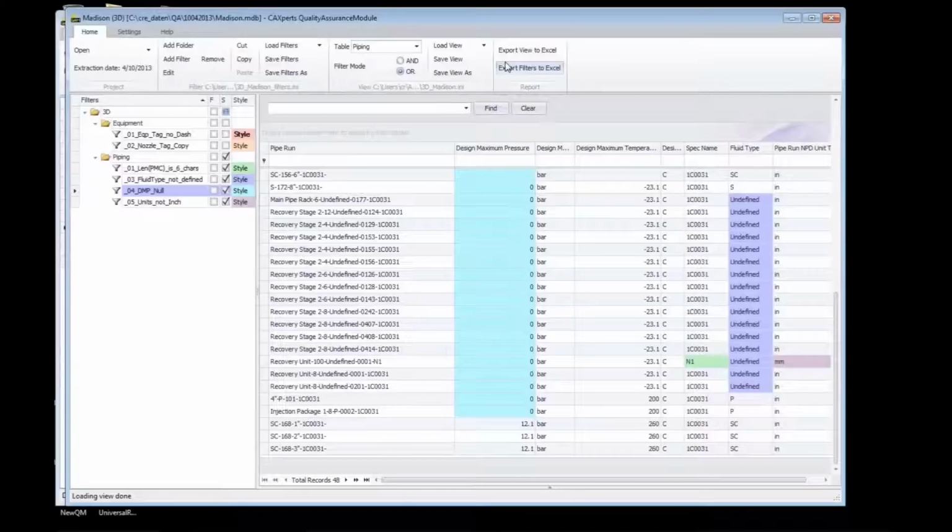Okay, maybe last word from my side. These reports can also be configured to run in batch. So if you define a rule set for P&ID, a rule set for 3D or for SPI, you can also generate batch reports so that in the end, when you come in the office, you will find the checks automatically lying on the table, or at least lying on your computer. Okay, so thank you from my side, and I will hand back to Andy.